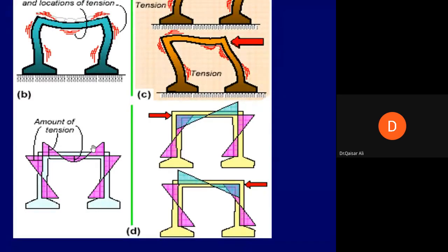So at the right end of the beam, you have a negative bending moment, which causes tensile stress in the upper fibers of the beam. Normally we will provide some reinforcement for this, we know. However, now you have an additional bending moment diagram here, coming from the earthquake analysis. This bending moment must be added to this bending moment for the final calculation of area of steel and placement of reinforcement in the top fibers of the beam.